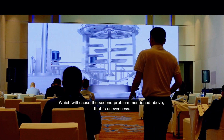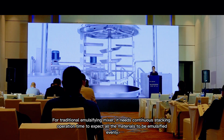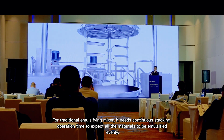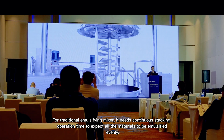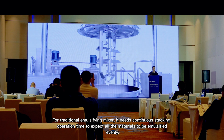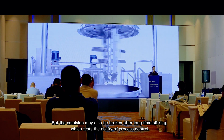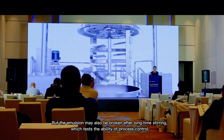Which will cause the second problem mentioned above: unevenness. For a traditional emulsifying mixer, it needs continuous stirring and operation time to expect all the materials to be emulsified evenly. But the emulsion may also be broken after long stirring, which tests the ability of process control.